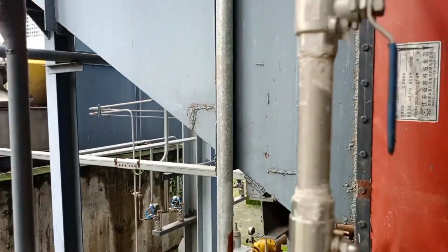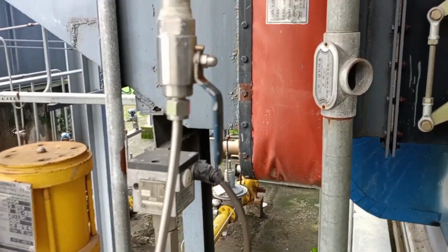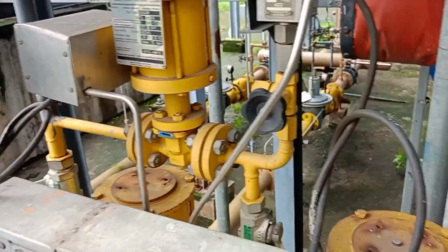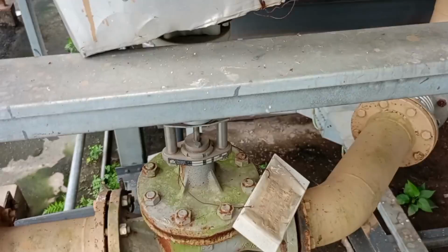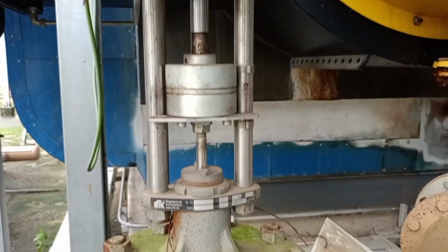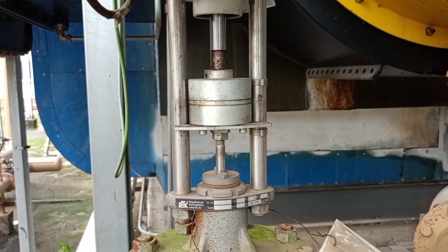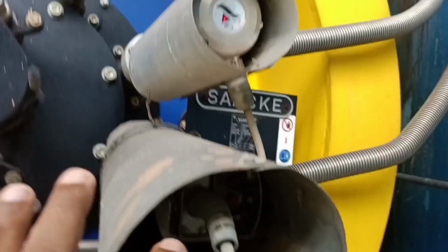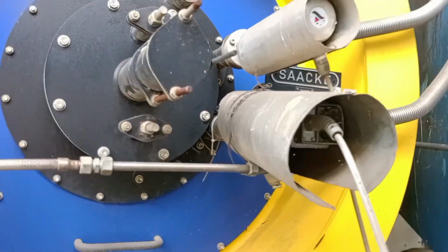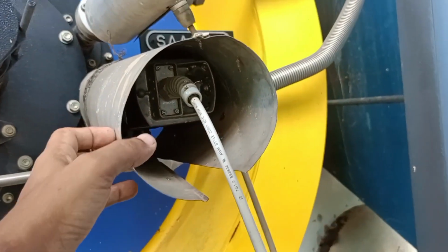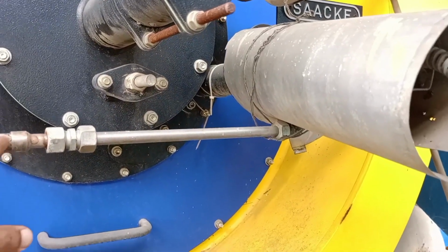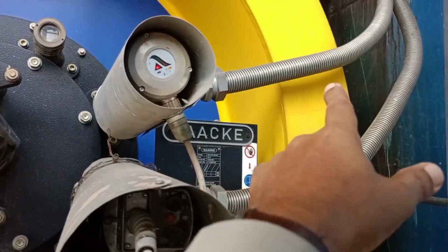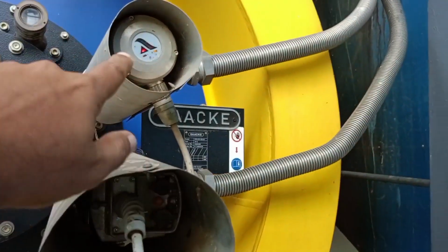At first, when the burner is started, this vent valve is in open condition, this block valve is in closed position, and the gas control valve remains at 0 position. That is the closed position. Now it is 0. Also here, this unit is the flame detector, and this is the igniter. To this igniter, here is the gas flow line, and here is the air flow line. The flame detector also has an air line for cleaning its pipeline.